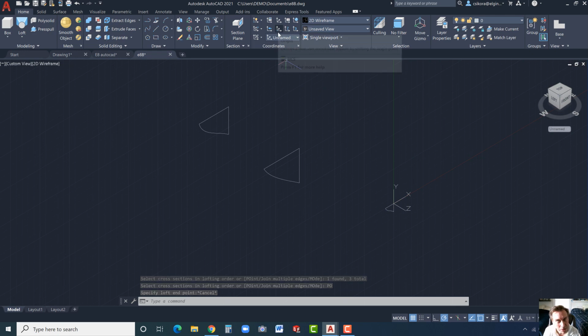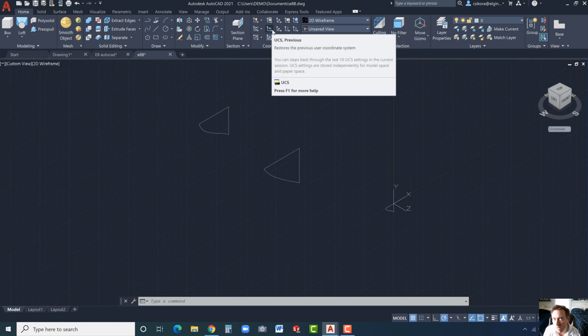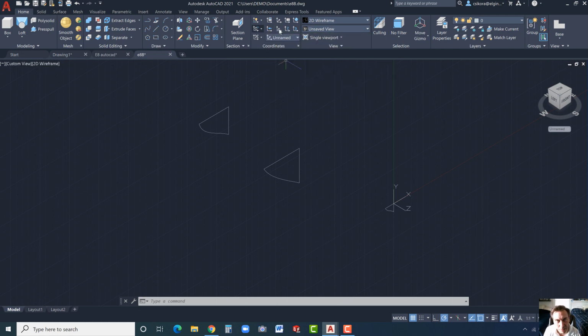And I know we could probably do it without creating this, but again, those of you who are using Inventor or some of the other plane-based systems, this is going to make more sense. So go to Z-axis, drag this forward, and we only want it 1 inch. And then make sure it's facing forward. Click. All right, now we should be able to do our loft.